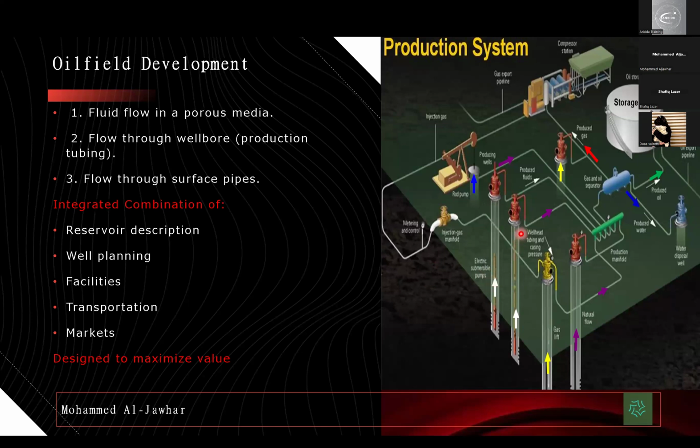So how many wells, where they should be located, to which depth, what are the facilities, what is the Christmas tree type, what is the casing and tubing type, where should the perforations be, and the flow lines. If it's secondary recovery, when you should convert some wells to produce with ESP, for instance.